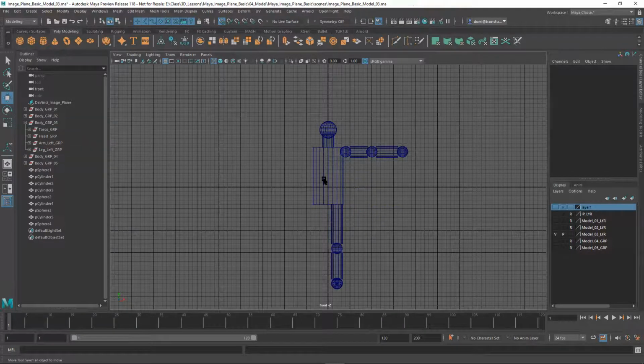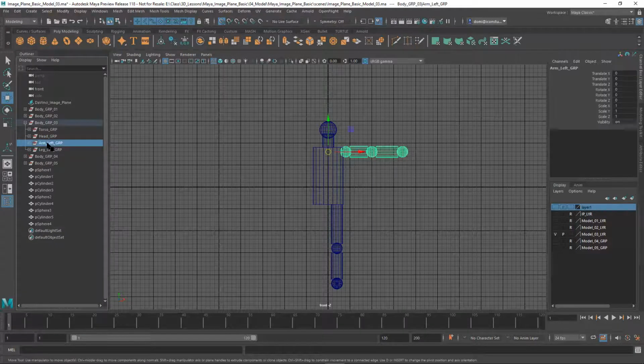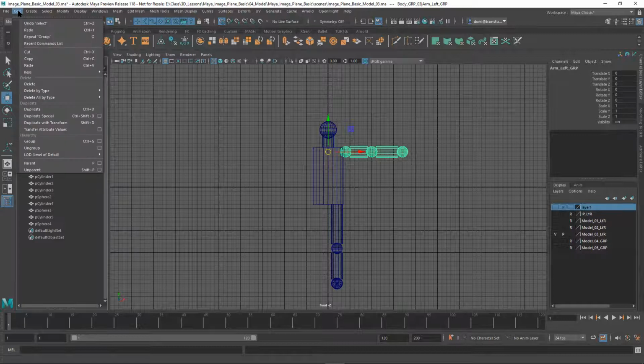Now those are on the 0 lines. These parts you don't have, so if you did this lesson, don't worry about it, just do this in the lesson manually. I'm just showing you some tricks for future reference. Now I want to mirror this whole thing over in that direction. This is on the x-axis, so let's go in the x direction. You go to edit, you need to know the axes you're rotating around, and you go to duplicate special.